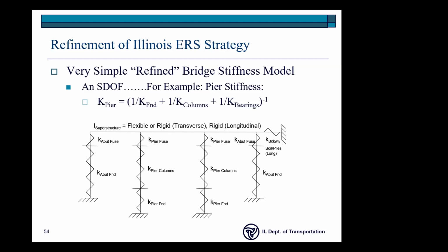But it is well known that the damping, generally speaking, is probably a lot more than what is assumed in design. Unless you have a very complex and expensive bridge, we would not use those types of techniques to estimate what the true damping is.